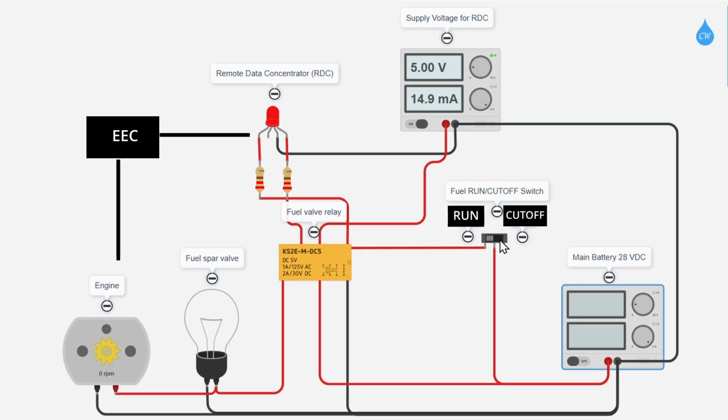If that graphic that we saw before is correct, and this RDC gets a voltage signal from the switch, if this is how it works, man, this is not good, like I said before. Because this fuel cutoff signal can be simulated or duplicated by cutting voltage to that switch.